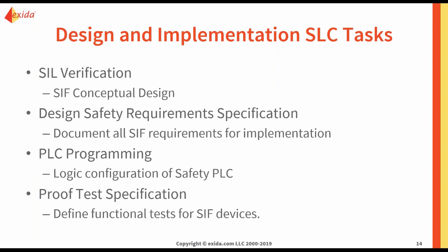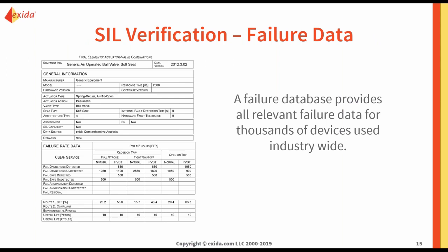Well, how exactly can our tool address all of this? And as you can see, just like the analysis phase of the life cycle, it's a lot to do, and having a streamlined work process and a tool to aid that work process can be very, very helpful. So we're going to walk through exactly how we would handle this in the tool. One of the major components of your conceptual SIF design is knowing how likely it is that the devices in your SIF would fail. So you need a lot of data. You need data for your failure rates, your useful life, your proof test coverage, things like that.